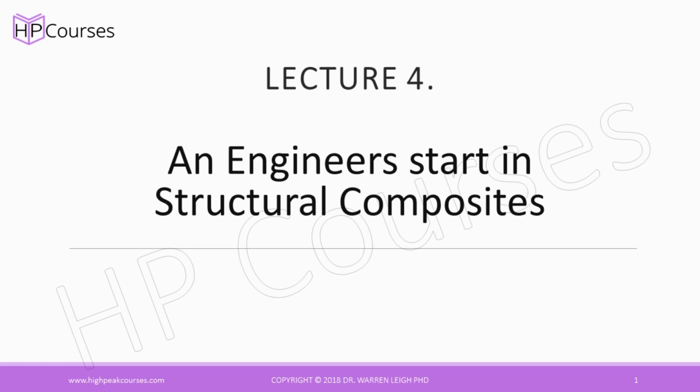of angle ply layers. That is, single plies laid at an angle of 45 degrees and minus 45 degrees, known as plus minus 45. These examinations are to demonstrate the effects on the mechanical properties of a composite by adding angle plies to this laminate. Towards the end of the lecture, the initial size and stress analysis of two simple beams will be made using the composite properties that we have designed in this lecture.